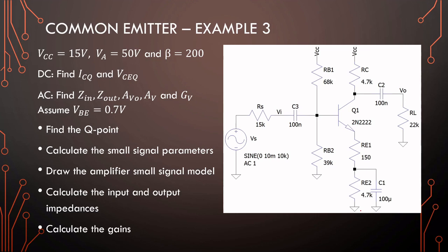Right. So if we do the DC analysis, this section is going to go away, this section is going to go away, and this capacitor will disappear. Okay, so in the DC bias, we will see both of these resistors in series. So RE1 plus RE2. If RE1 is very small and you're just using RE2, it won't matter as much.